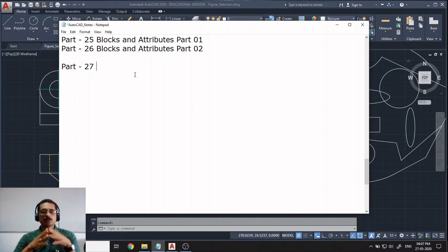And I hope you remember that for a window, the first point of the rectangle should be on the left side and the second point on the right-hand side. Similarly, for crossing it is vice versa: we start from the right side and end on the left side. This is what we discussed in part 7 of the series.